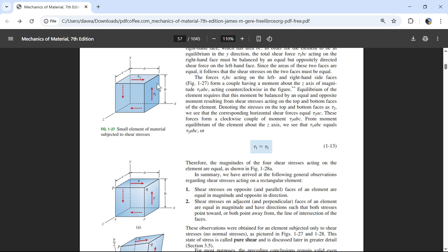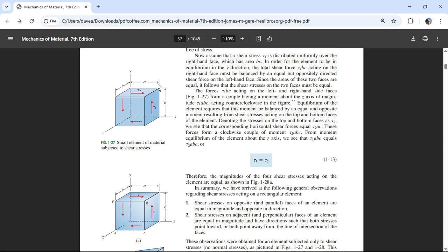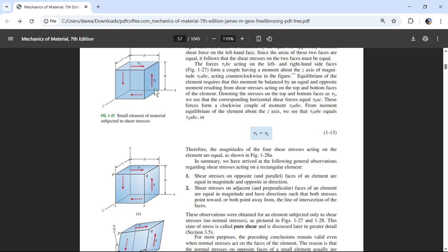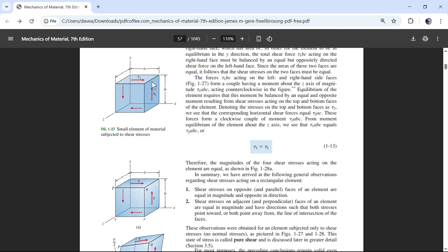Cool. And that is useful because I swear, I think the materials mechanics books would get way better if every time they drew a shear stress diagram, where you have the pressures on the faces of an element, they also did a free body diagram where you have a force up. And if we had a force up on this surface, that's going to be an upward force in the y direction. So the sum of our forces has to be zero, the forces have to be equal and opposite. And so we have to come over to this face and have a downward force.